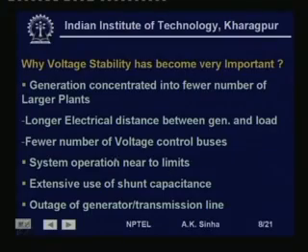So, this is another reason why voltage instability is coming into the picture: the loads are now very high, and the power flowing on these transmission lines is very near to their limits, and therefore the voltage at the receiving end is also at a much lower value, and the margins available are very small.